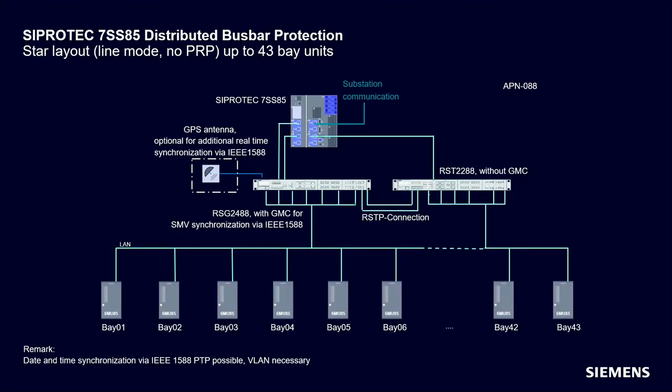Each PD module is covered by a physically separated ring, so no mix of information was possible. Here at the switches, we would have a mix, and it could be possible that, let's assume, Ethernet PD module 1 should cover bay 1 to bay 16 and so on.